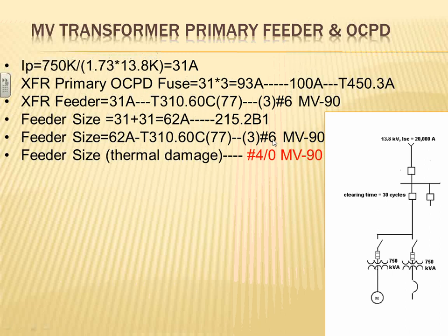Now, the reason why I threw this one in is because this is sizing it based on the load. When it comes to the medium voltage, there are two sizes that you have to be aware of. One is based on the load, and the other one is based on the short circuit withstand rating. Now, great, your number 6 will function properly under normal operating conditions. Now, what happens if you have a short circuit right into this medium voltage? Would this medium voltage be able to withstand the short circuit inside it, or would it burn? How would you know, right?